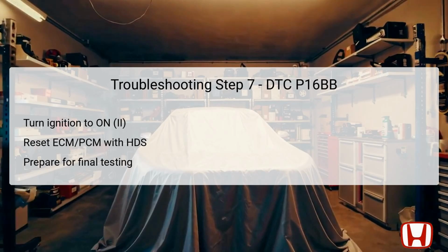Following this reset, it's necessary to perform the ECM/PCM idle learn procedure, a process that allows the module to register all new data regarding the vehicle's idle settings and various systems that may have had adjustments made. Restarting the engine after this step readies the system for thorough checks under the same electrical load conditions while maintaining temperature control and other requirements.